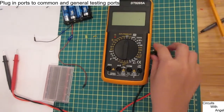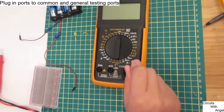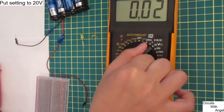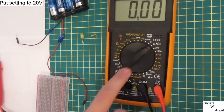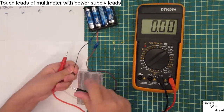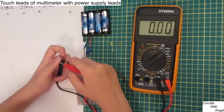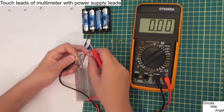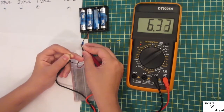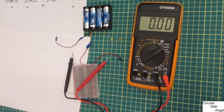So we are going to build a simple LED circuit. We are going to measure our power supply, pretending we don't already know the answer. We'll plug in our ports, 200 milliamps and common. Then we are going to put the setting on the multimeter to 20 volts. The other setting goes to 2 volts, and we can tell that we have more than that since each battery has 1.5 volts in it, and we have 4 1.5 batteries. It is 6.3 volts. These are fresh batteries, so they have a bit more charge in them. We will round that to just 6 volts.